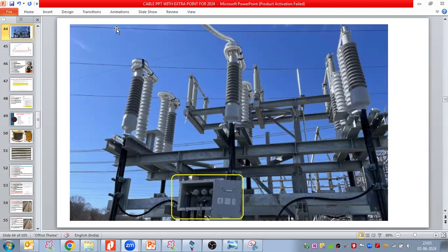Normally it will be like that, sir. If it is underground cable, it will all be backfilled. So wherever the joint is, there will be a joint bay, which will be accessible. The provision will be there, so it would be convenient to do it at the joint point.